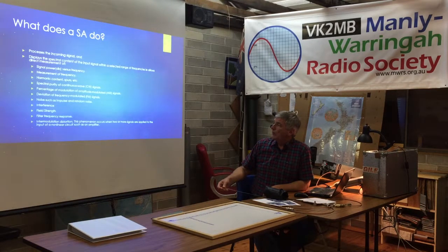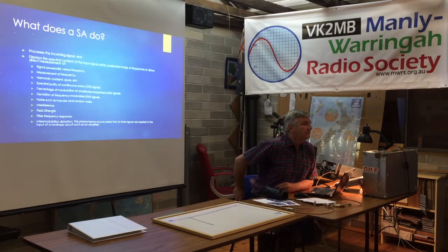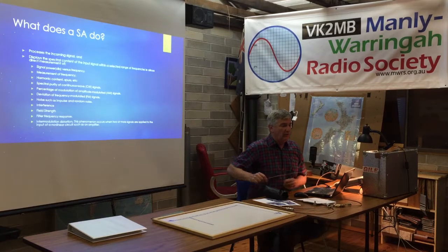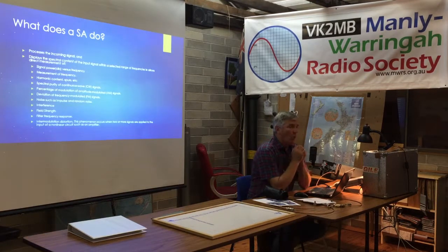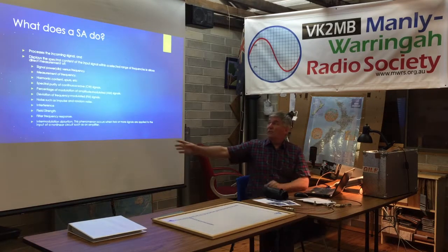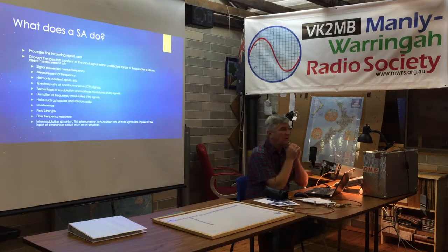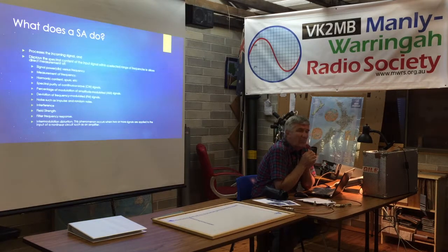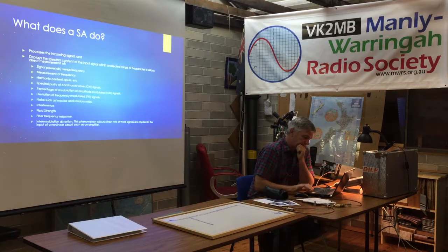And that, as we all know, occurs when two or more signals are applied to the input of a nonlinear device. Spectrum analyzers can work from audio up into the tens of gigs easily, perhaps not in the same box, but they do cover that range. Some people use them just for audio and look specifically for distortion and IMs in audio circuits, high-end audio. But we typically just use it for RF, so that's what I'll be focusing on in this talk.